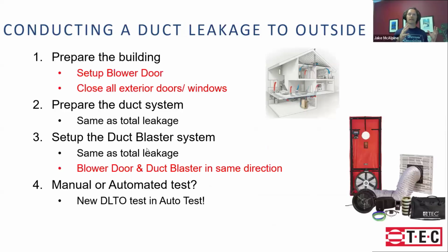I'm going to go back to total duct leakage and just say how the leakage to the outside is different than the total leakage test. So when we're preparing our building, obviously we're going to set up a blower door, which we didn't have before. Another big thing is that we need to pressurize the house. So before we were relieving the pressure in the house, now this changes.